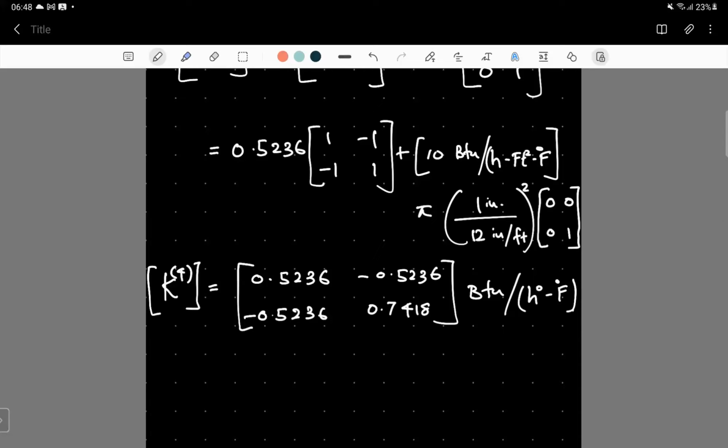So then we have already found the element stiffness matrices. Then we have to use again the equations which we developed in the previous session to obtain the element force matrices. Analogous to structural problems, our element stiffness matrices relate to F equals K times D. K refers to the element stiffness matrix, F refers to the force matrix, and D refers to the displacement.